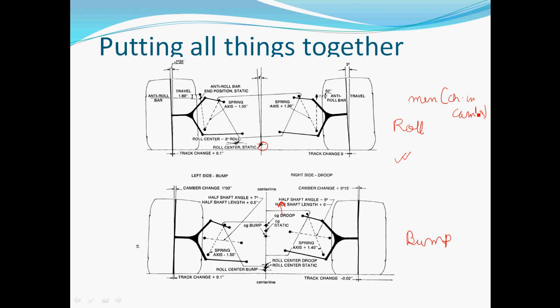Say your outer wheel changes from 0 degree to plus 2 degree. If I give initially minus 2 degree, then at the time of cornering it will change to 0 degree, and the moment it changes to 0 degree, it will have maximum traction, and it will have a greater cornering force and greater cornering ability.